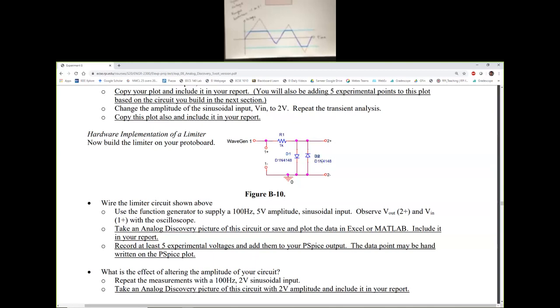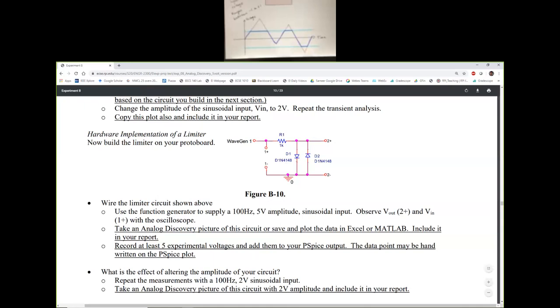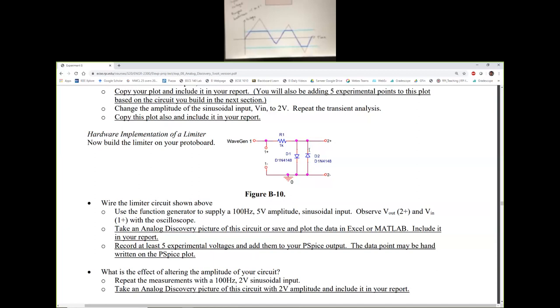Now clearly, if you want that voltage to not get limited to plus and minus 0.7, but instead limit to, for example, plus 2.1 and negative 1.4, then we can have three diodes facing down over here and two diodes facing up over there.